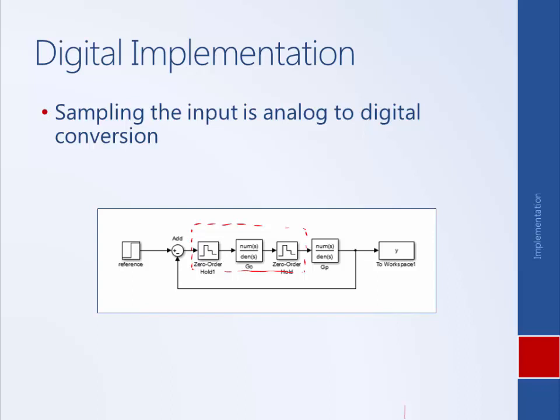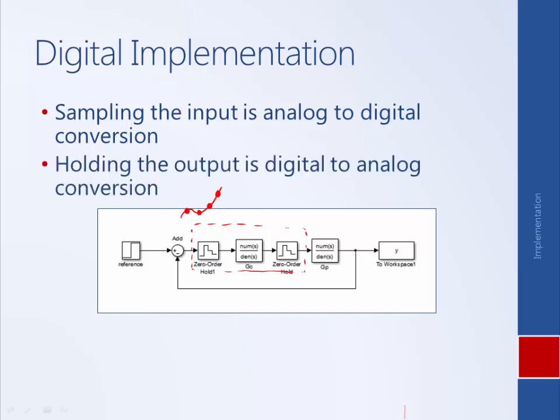So you can sort of imagine, we have this continuous output and this continuous command, and periodically the computer will sample that reference, it'll sample that sensor, and then it'll use that data point in its algorithm when it computes the control output. And so there's some frequency with which this sampling occurs and the program runs. It'll run once every 10 milliseconds or whatever. Similarly, the computer program generates an output periodically.